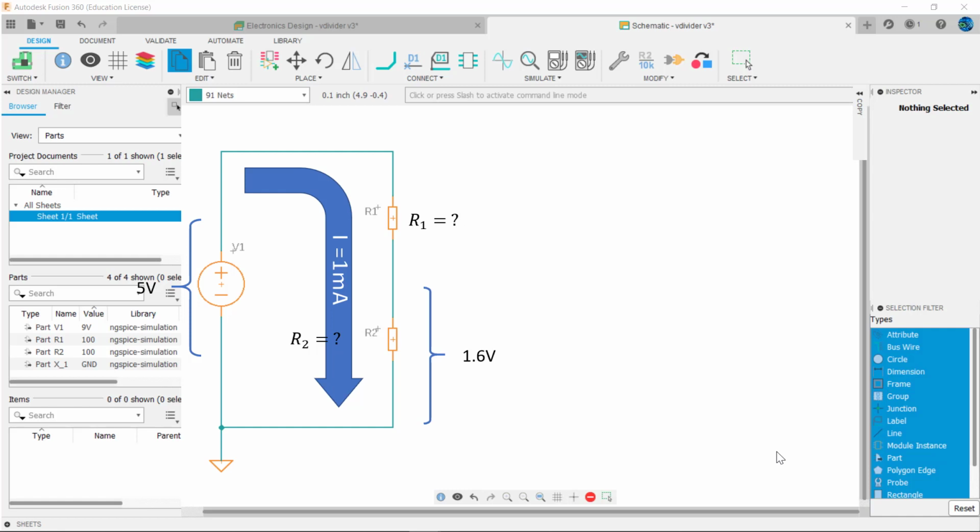And now we just need to calculate the resistor values using Ohm's law and/or the characteristics of series circuits. Ohm's law tells us that R1 equals the voltage across R1 divided by the current through R1. And we know voltage divides up amongst devices in series, so the voltage across R1 equals the V applied to the circuit minus VR2. Formally, this is called Kirchhoff's voltage law.